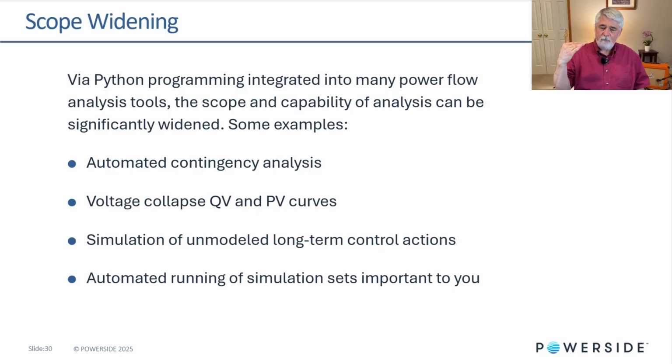Maybe you have something in your plant process where the loading is changing over time. Every minute or so, or every 5 minutes, it's changing significantly, and you want to know what that's doing to your overall demand profile. You can perform these types of simulations. You can write a Python program that'll take your loading data, inject it, solve the power flow, inject the next case, solve a power flow, inject, repeat, and then store and save the results for yourself.